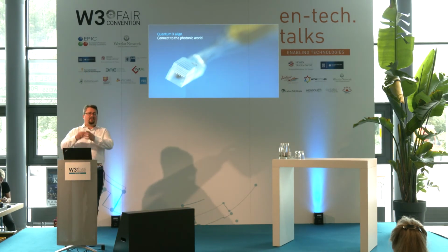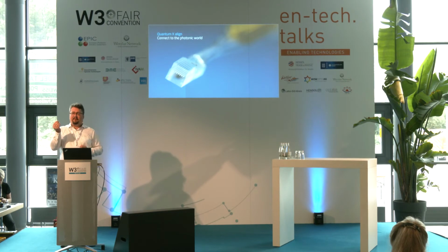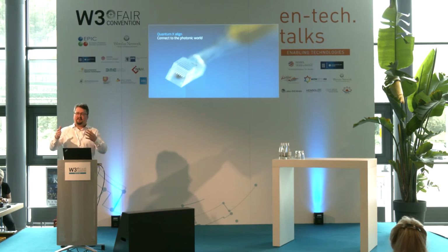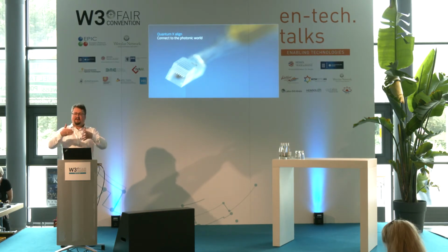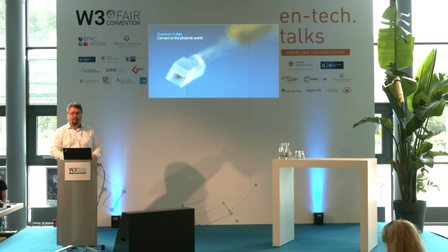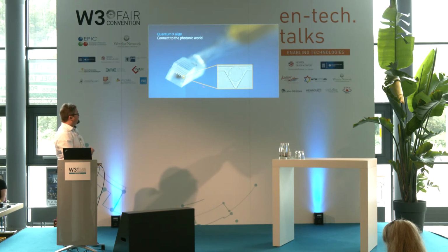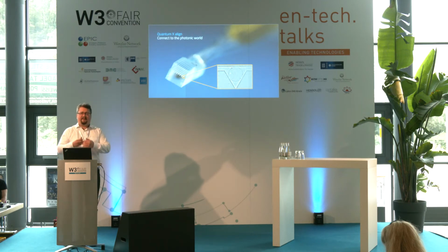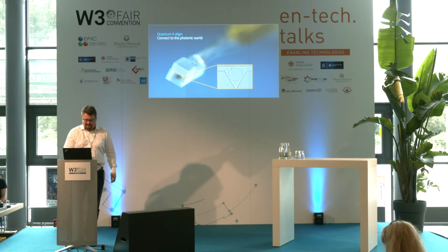So now you're not just dealing with an individual fiber optical cable, but you want to do it with many because you want to do parallel communication. You want to interchange several quantum states at once. So you make arrays of fiber cables, and they are typically mounted in such a system. So there's a glass block down here, glass block up here, and there are these V-shaped grooves into which the fiber optical cables are pushed so that they are in a defined position, and then the front is polished, and now you have an array of fibers in defined positions.